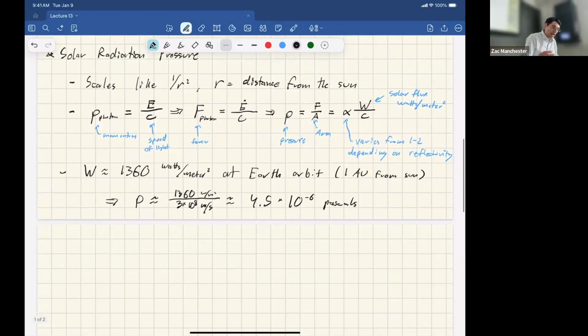It makes a difference. And back to that 600 kilometer number, 600 kilometers is about where drag and solar pressure break even, where they're about the same. So that's kind of where that number comes from. So below about 600 kilometers, drag completely dominates, and solar pressure, relatively speaking, doesn't matter very much.